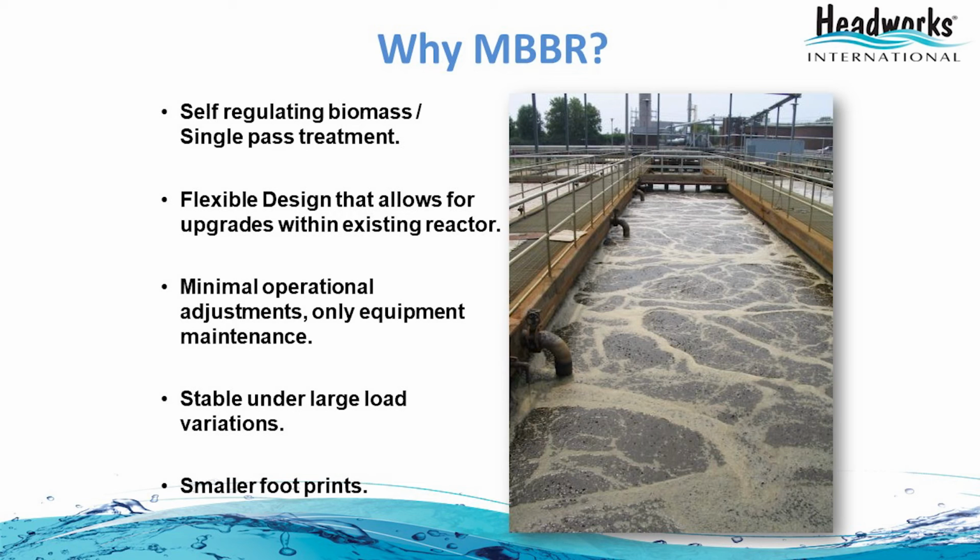So why MBBR or fixed film process? The main reason is that it's self-regulating biomass. The bacteria will grow and shrink depending on the load that comes into the reactor. So there is no need to adjust the return flows or any other parameters within the tank. The biofilm will automatically shrink and grow depending on the load. So it allows for flexible designs.